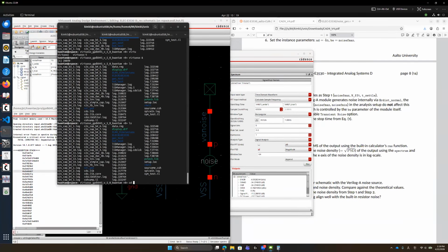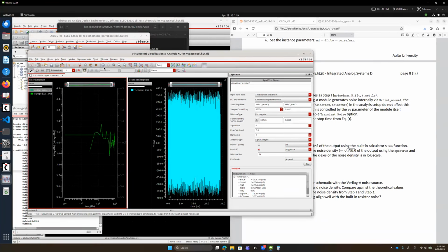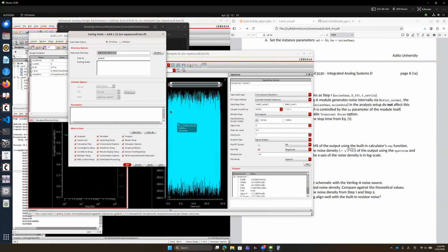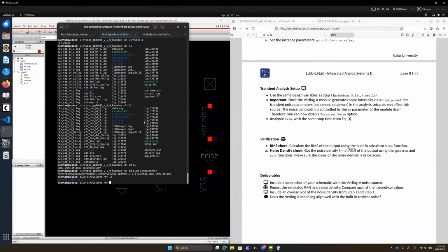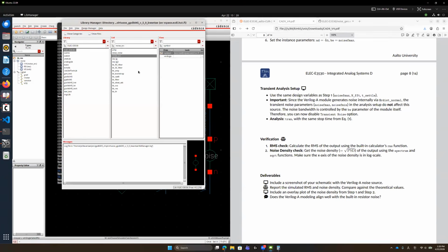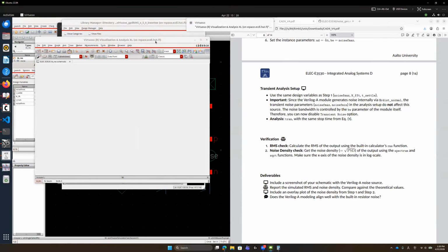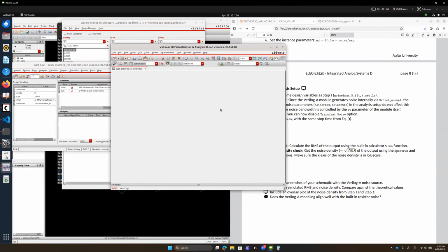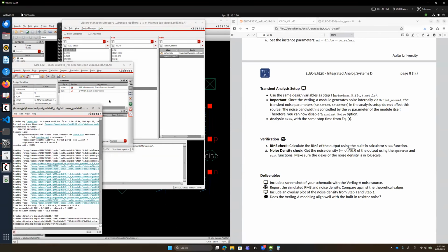So let me go to this simulation setup and make sure. Yeah, we don't have any other choice. We have to close it. Basically, you can remove it because this is simulation data. It's not important design data. It is just simulated data. And then after removing it, go back to register. Yep. And I think now it is clear, right? Because we removed the simulated data, nothing is left. And I believe if we run the simulation again, it can run correctly. Okay, good.